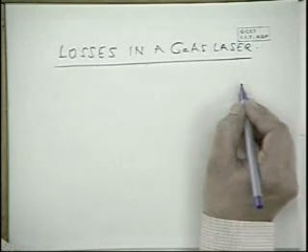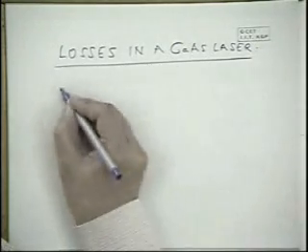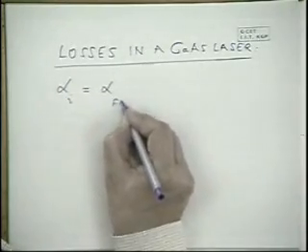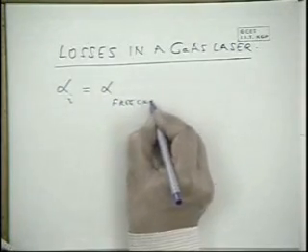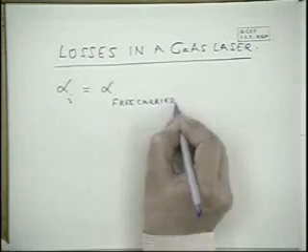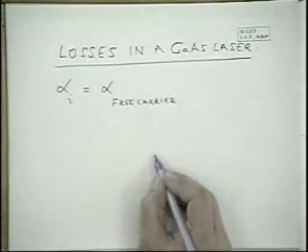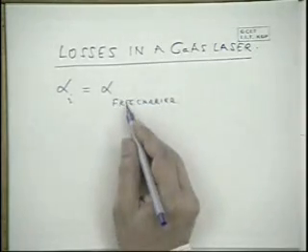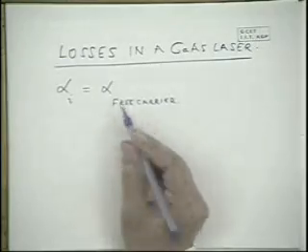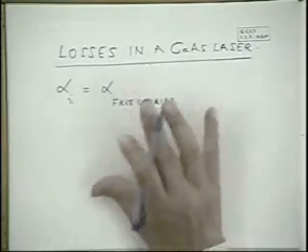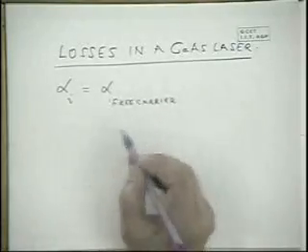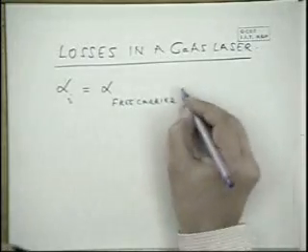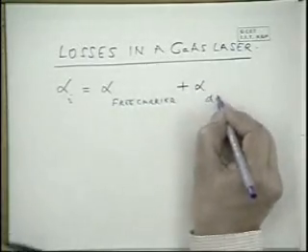That determines the alphas. Alpha will be alpha free carrier. Remember when, in absorption mechanisms of a semiconductor, I talked about free carrier absorption, which is within the band. For heavily doped materials, this is reasonably high. You cannot neglect it. And as you know, for PN junction semiconductor lasers, in order to get the population inversion condition, the materials are reasonably heavily doped, 10 to the power 17, 18. Plus there is a term alpha diffraction.